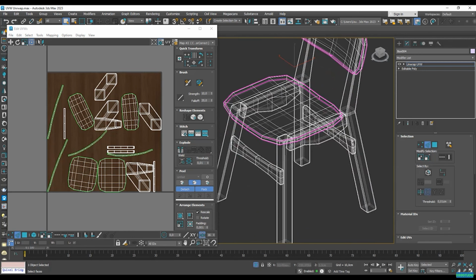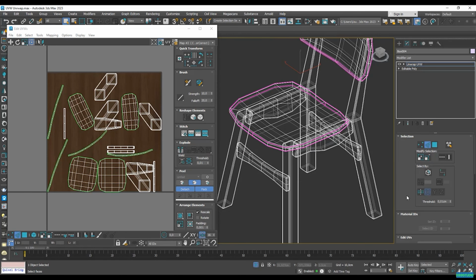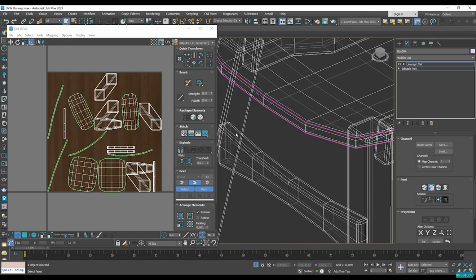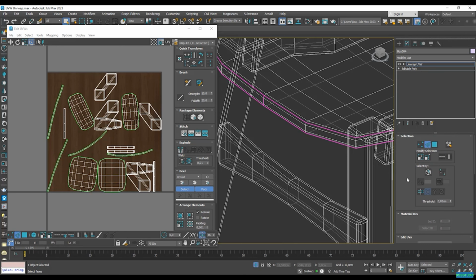All right, for the next parts, if you remember that I told you that when we're using this peel mode, which is an interactive way of cutting our surfaces, we can't really use a Ctrl-Z. So for these parts that are a bit more hard to do, I'm going to disable my peel mode and go ahead and make it the other way. So I'm just going to first select my edges and then convert it to seams, so that if I make any mistake, I can actually unselect my edges and go back a step.